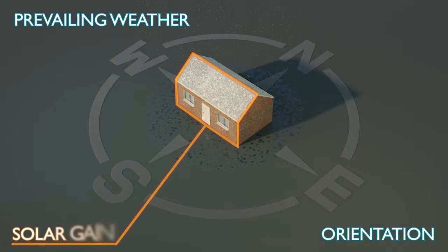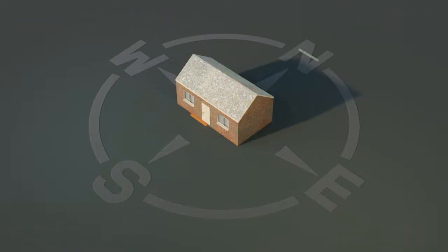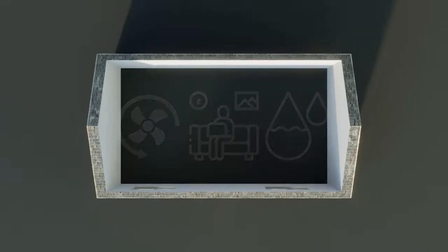The hygrothermal performance of south-facing walls exposed to the sun will be different from a shaded north-facing wall, and striking a balance between these is important. Finally, the internal environment and occupancy patterns must be considered. The type of function of the building establishes the moisture load it's likely to experience, and the requirements for ventilation of the habitable spaces. The impact of wet trades on these conditions should also be factored in, as any works involving concrete, plastering, etc. will increase the initial moisture load considerably.